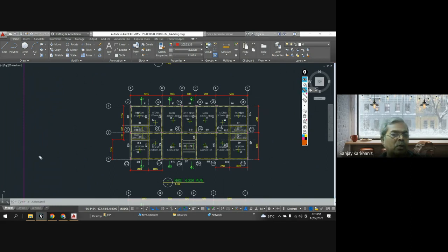Let me clear you. See, this moment is your outcome. This depends on your loading and span. Okay, so I will talk about this Mu design. So the design moment is the outcome of your analysis, and if I talk MUR, that is the capacity of that column to carry out the moment. Okay, so this will affect.